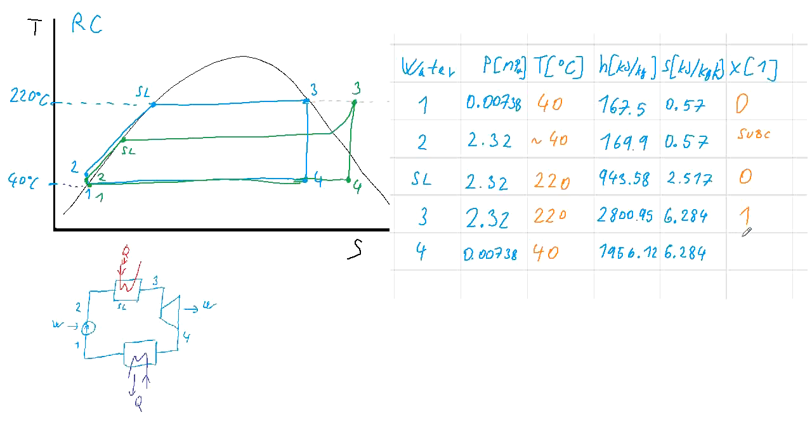And also we can get the steam quality, which is 0.743, which is actually pretty low for some turbine to actually survive with this. Perhaps some volumetric expander could handle that, but turbines basically not. But this is a theoretical calculation, so we will say that the turbine would be able to stand this.